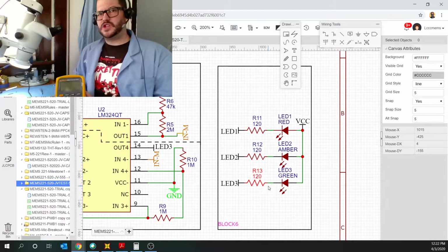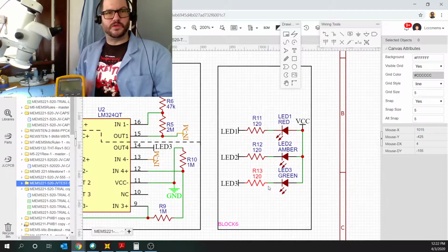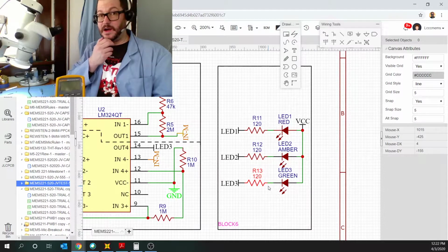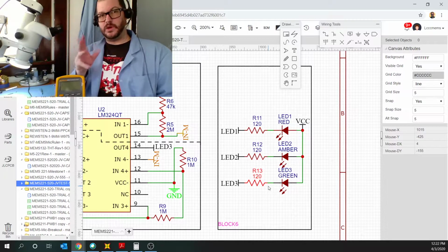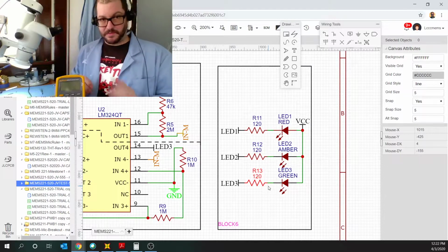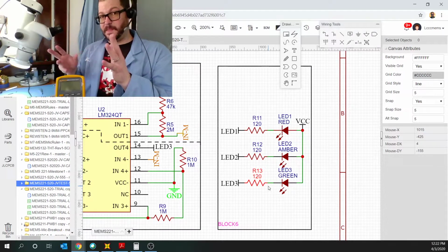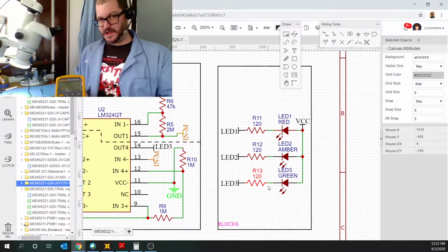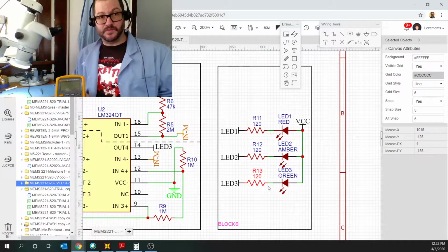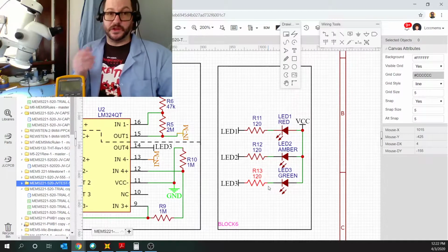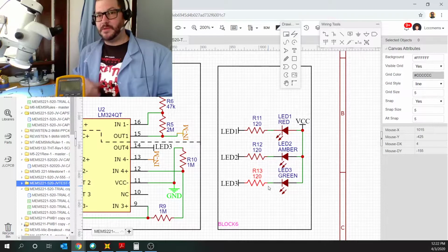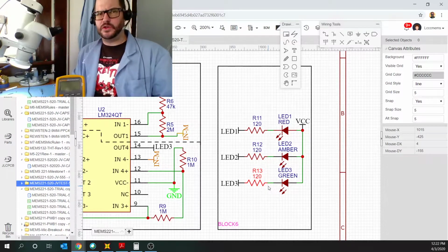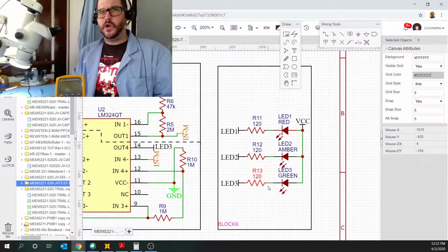Now, in a nutshell, LEDs are sort of one-way devices for electricity. If the higher voltage is on the anode and the lower voltage is on the cathode, that's what will eventually help to send current down through the LED. But if the higher voltage is on the cathode and the lower voltage is on the anode, then the LED effectively stops any current from flowing through until it breaks eventually with a large enough difference in the voltage between there. But LEDs are also sort of tollways.